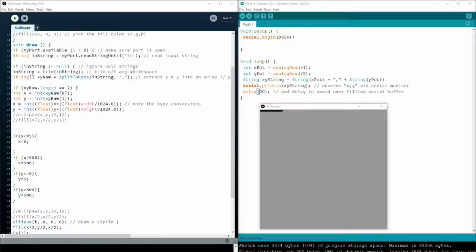As you saw just a moment ago, the potentiometer is connected to the Arduino via the analog pins, and it's reading a voltage from 0 to 5 volts. Right now, as you can see, it's at 5 volts because the dot is all the way at the top of the screen. But I can change the voltage across the potentiometer by turning the knob. And as you can see, just like a real oscilloscope, once it gets to the end of its travel in the time component, which is on the x-axis, the oscilloscope resets and goes back to the beginning and continues tracing the voltage.